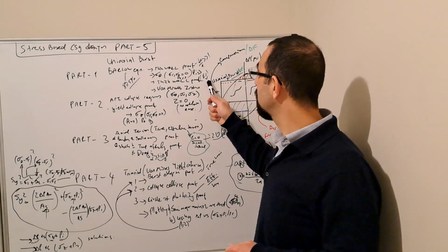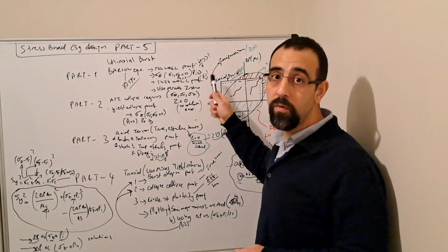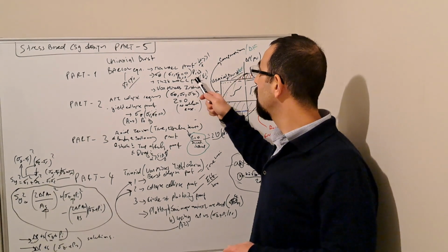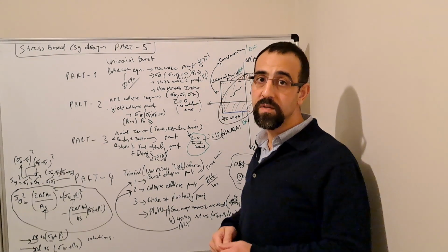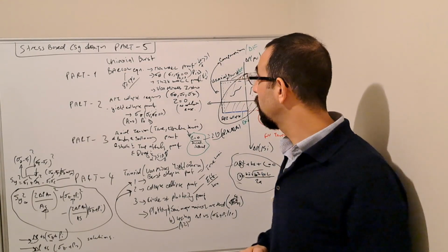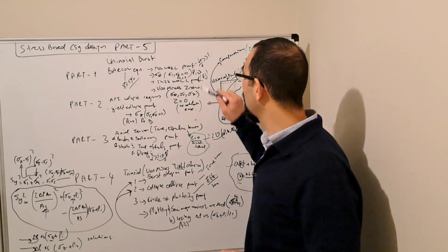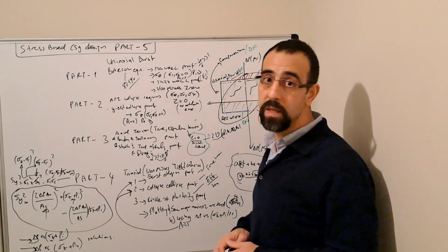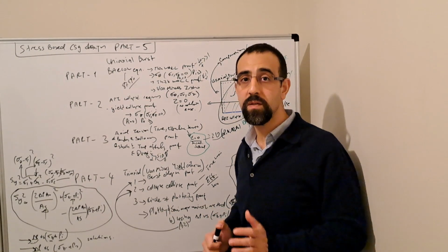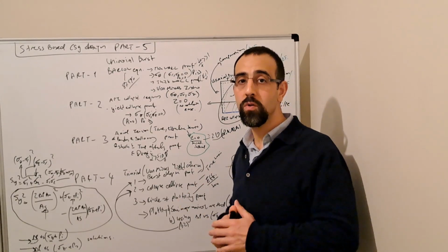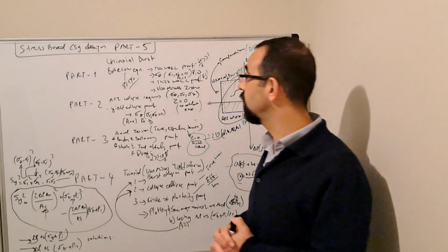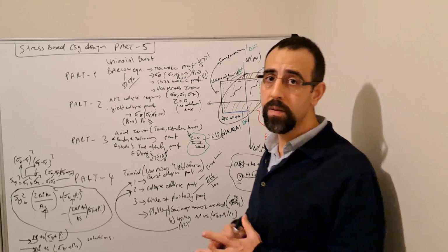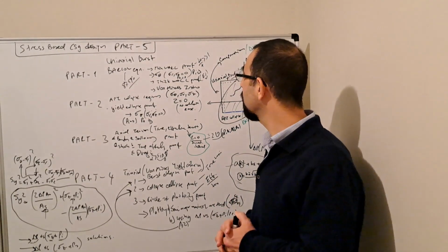So we solved the inner wall for the radial stress, and by assuming the axial stress being zero, we put this into the von Mises yield criterion and came up with another internal pressure. If you remember, this internal pressure was very similar to the Barlow equation, with a very small difference.